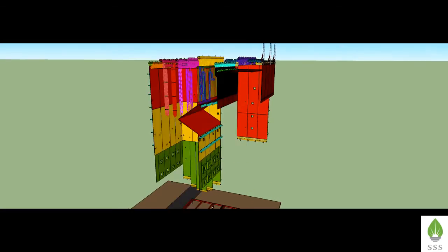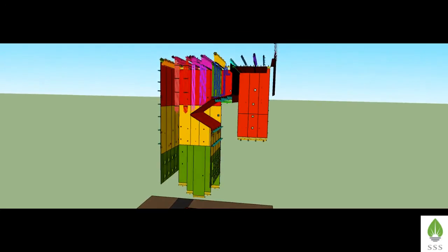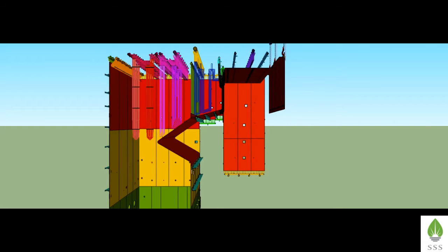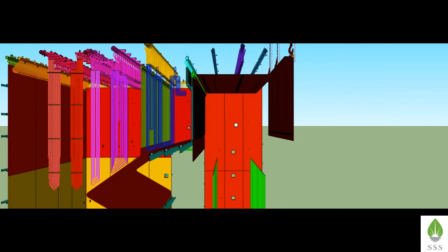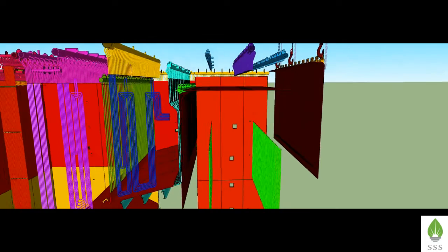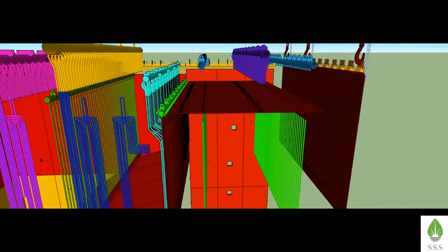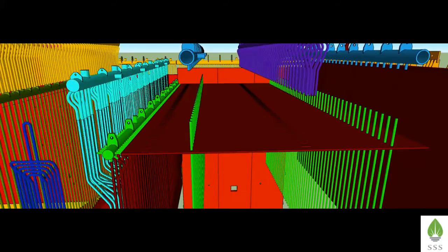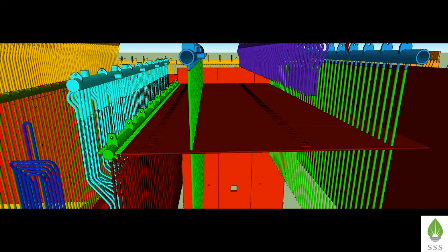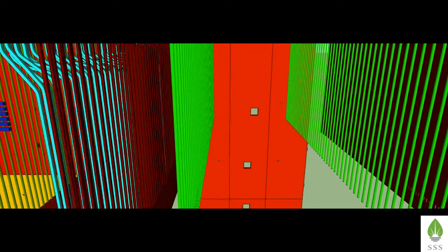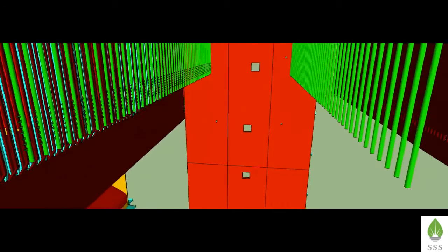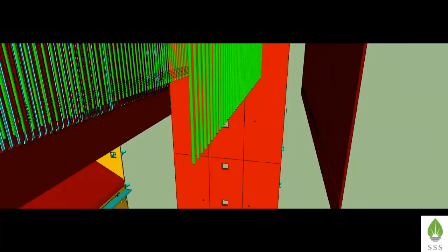Stinger tubes are the loose tubes which extend from economiser intermediate header to economiser outlet header. Also stinger tubes aid in supporting the reheater horizontal coil and primary superheater horizontal coil. Insert all the stinger tubes of both front and rear economiser outlet header through the roof wall panel openings and weld with the headers. Stinger tubes connect the economiser intermediate header with the outlet header. Front stinger stubs are provided with arrangements to hold the reheater crossover tubes, whereas rear tubes are bare.